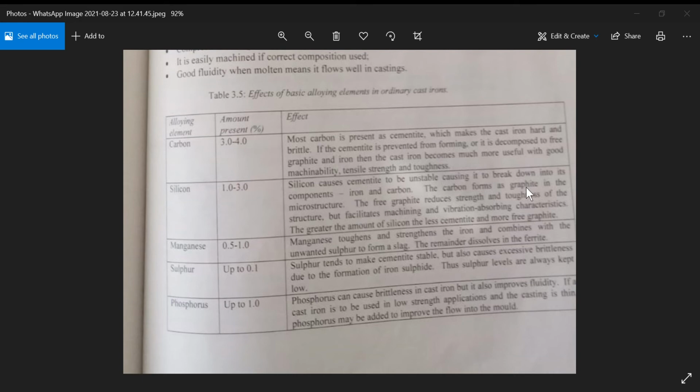Okay, now moving on. Now, when you look here, we've now got ferritic grey cast iron. We see these large graphite flakes are a lot larger as compared to this. So they're bigger, they're pointy. Think of them as like big cornflakes just stuck together. And this black line around here is the grain boundary. So that grain boundary is all ferrite, with voids or sections of large graphite flakes.